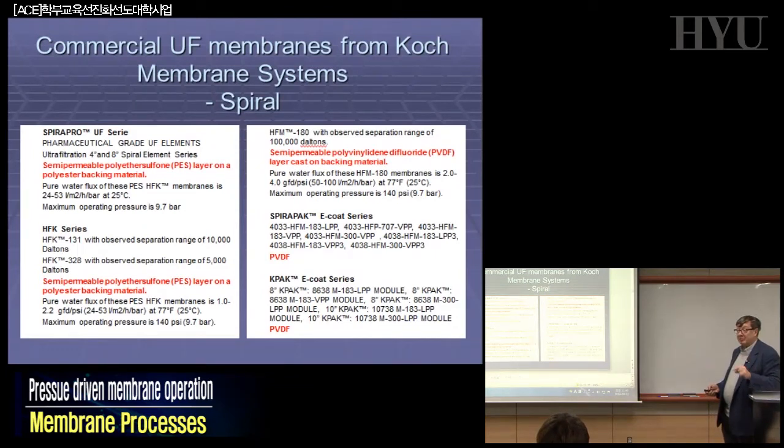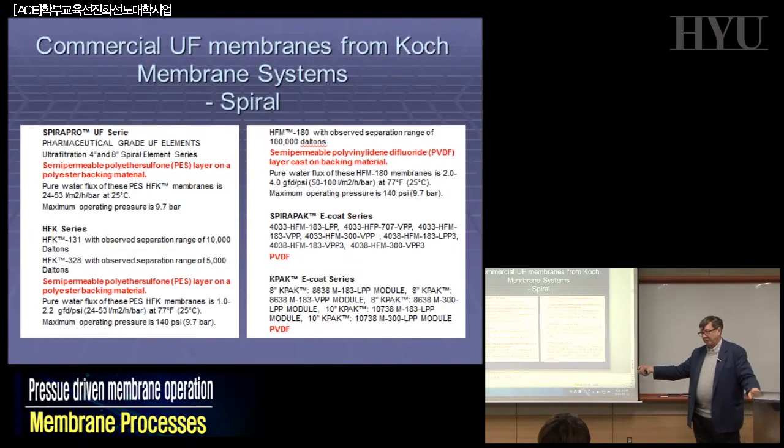If by mistake you change the quality of your color, so that instead of a cationic painting you have an anionic painting, and you forget to change the electrode positions in your ultrafiltration, and you put your car inside, in a few seconds you block everything. Because, in this case, the fouling phenomenon: if you change the ionic character of your painting, you have to change the ionic character of your membranes.